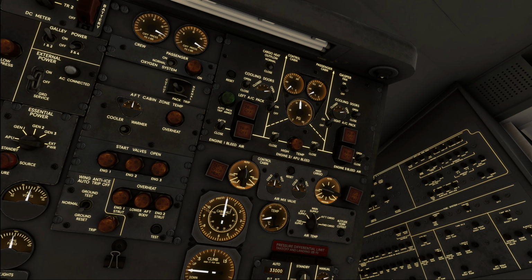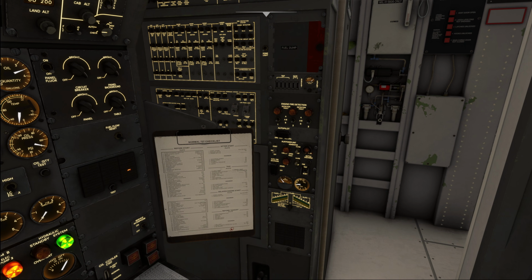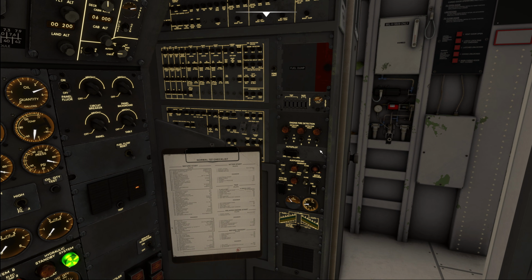So like this, it's in a shape where you've got a nicely cooled or warmed, depending on the season, cabin. We've got electrical power applied to the plane, and we made sure that enough operating fluids, let's call it that way, hydraulic fluid, oxygen, oil, etc., are on board the aircraft. So from here on, we now go into our aircraft system checks, and we start them on the aft part